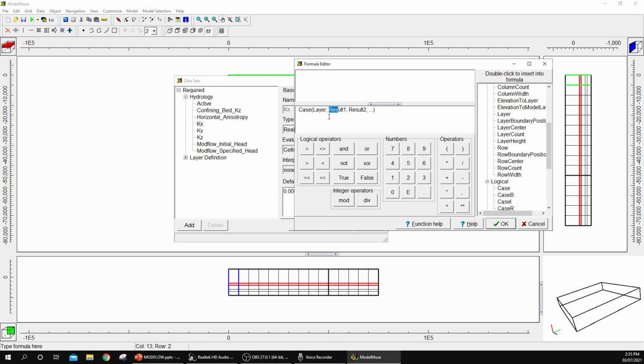And then from there, we just have to input the hydraulic conductivity values from layer 1, layer 2, layer 3, and layer 5. Alright, so let's start with layer 1, 0.001. So this is in meters per second. Alright. I will be explaining later on why this is in units of meters per second. And so that's for the upper aquifer.